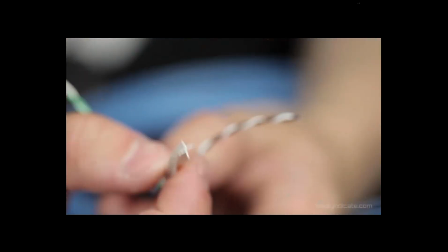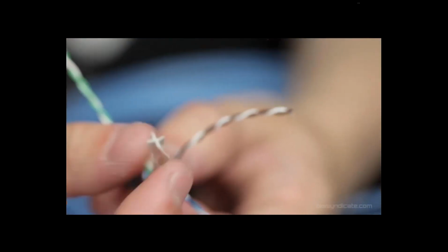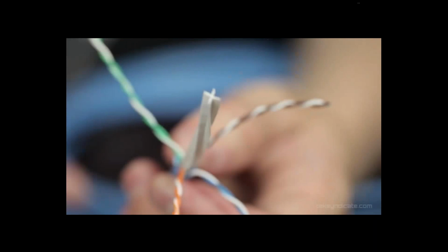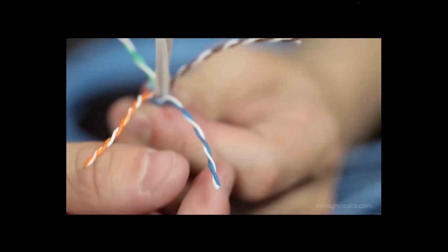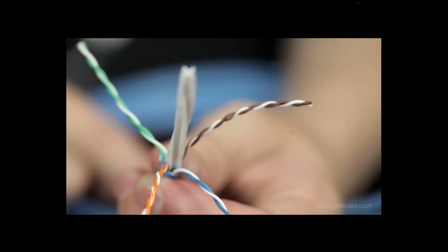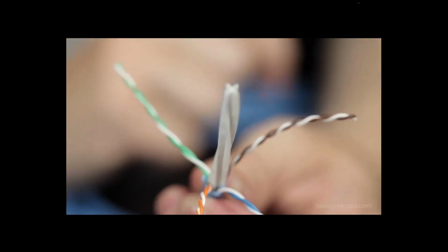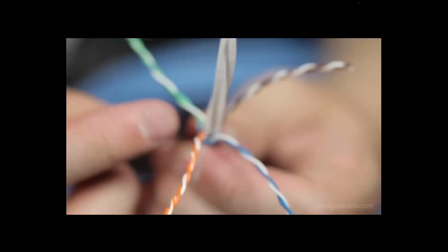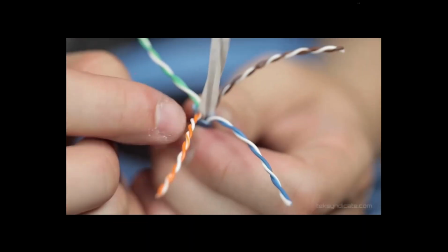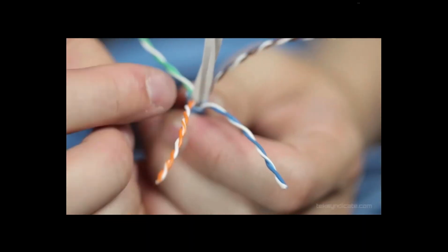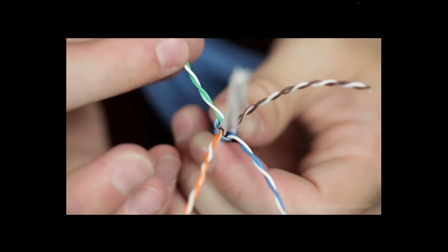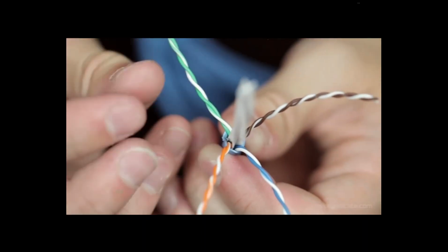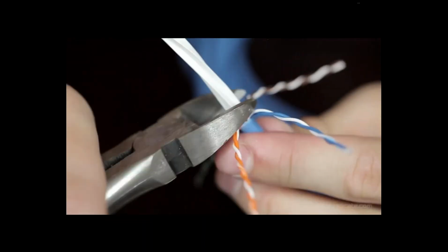This piece is just a big glop of insulation. It separates out all of the wires and runs the entire length of the cable. So each pair, as you can see the twist here, each pair is separate down the length of the cable. And they do this to, again, eliminate crosstalk, which is the electromagnetic noise generated by these wires with electricity flowing through them, so it does not crosstalk over to here. Or it does, but it's minimal. Very carefully, we want to just remove this bit of insulation because it just makes our lives a living hell.